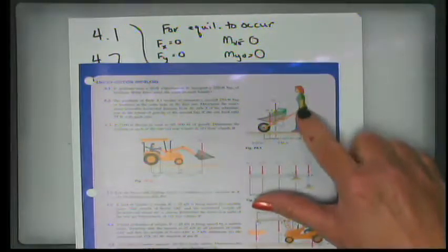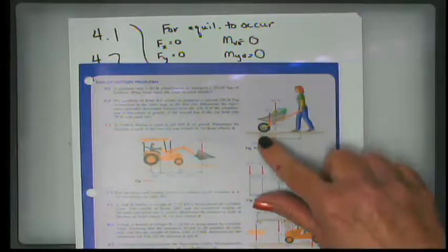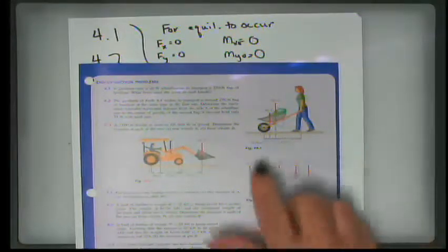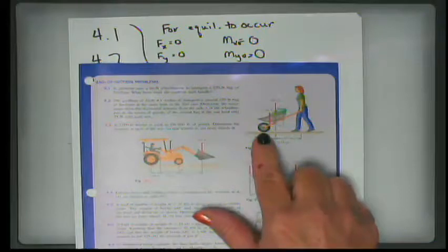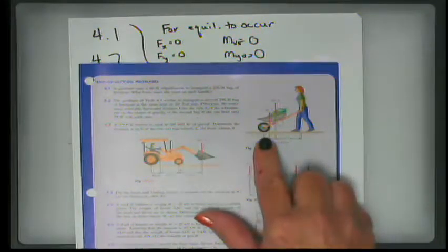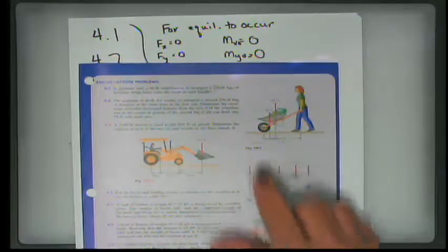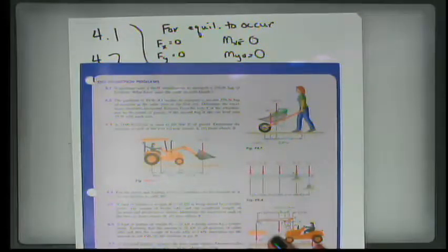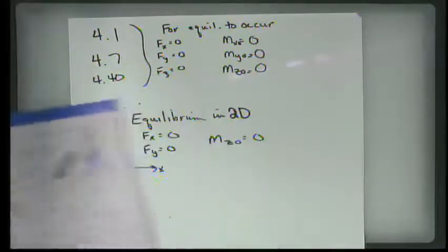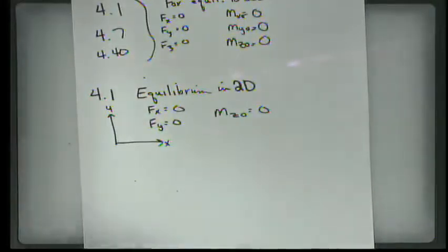So we can just say that this is 2 times that force, and there's a reactive force of the wheel. Now, just like in the support section that we just saw, the force on that wheel is only going to be vertical. And so using that information, we can determine what all of the unknowns are here.